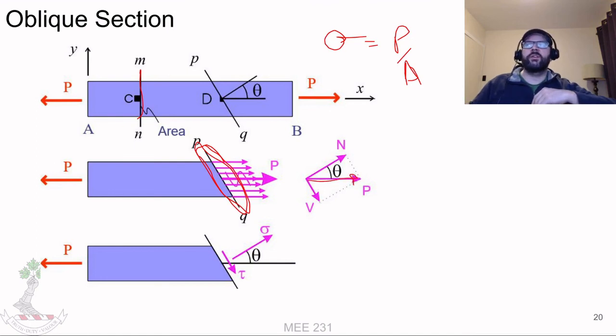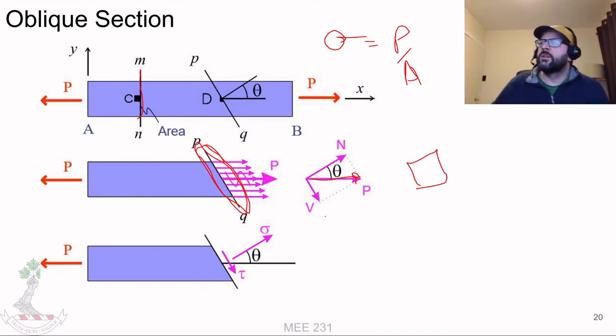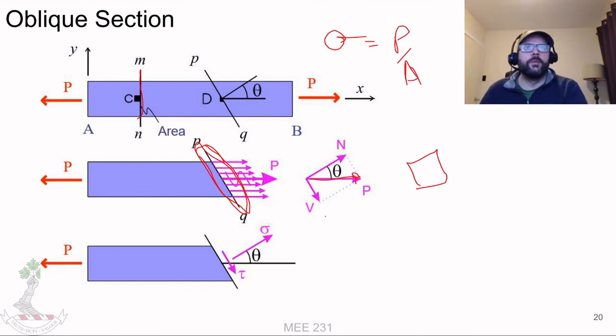But we're going to have to create it on the basis of some combination of shear stress and normal stress. So the fact that we are looking at things at a slant means that taking a section, if we're examining a cube that's also at a slant, then the stresses that would arise in order to keep that cube in equilibrium need to be shear stresses and normal stresses.